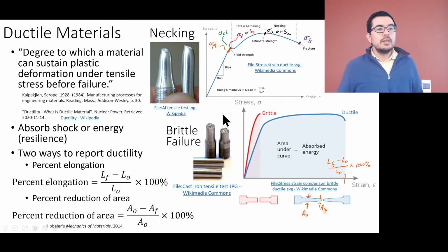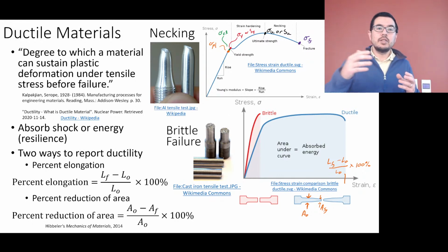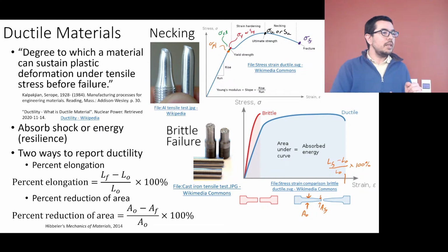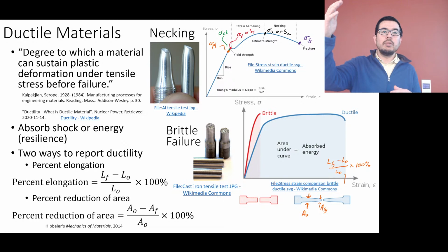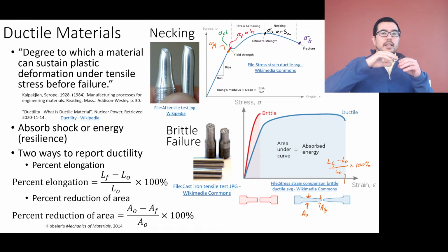Cast iron actually has a high amount of carbon in it, okay? So to be a steel, you need to have less than 0.2% carbon. Cast iron, although it's just iron, actually has more carbon than your standard steels do. And when you add that extra carbon, it becomes that rough surface, and the brittle fracture is something that we would expect.